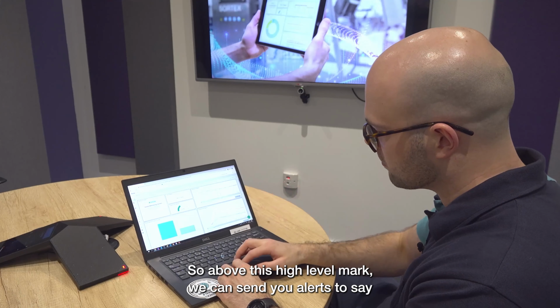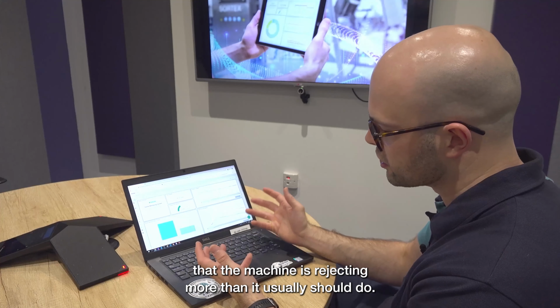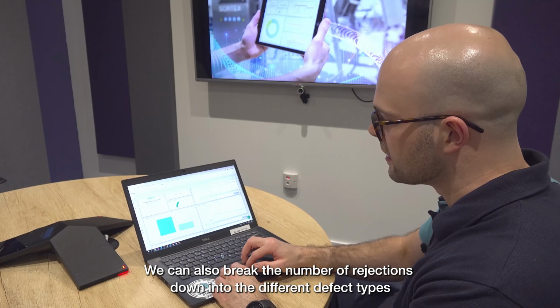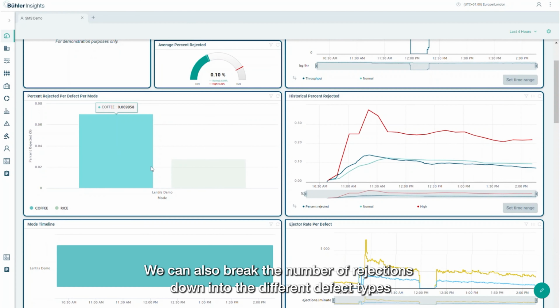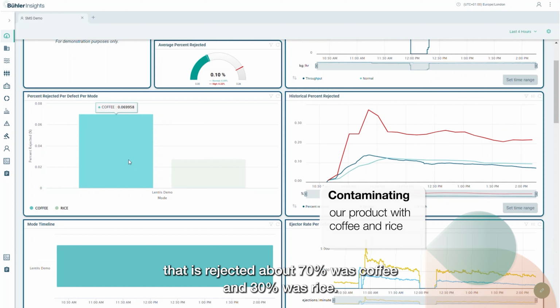So above this high level mark we can send you alerts to say that the machine is rejecting more than it usually should do. We can also break the number of rejections down into the different defect types. So for example here you can see that of that 0.1% that's rejected, about 70% was coffee and 30% was rice.